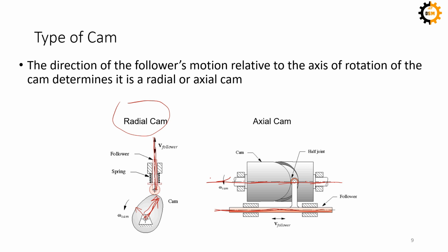Okay, if you see this left right side example again, this is also a roller type of follower based on the shape of follower, and it is translating because the follower is moving in translation. And another thing you see is it is form closed if this roller is entrapped within this track.